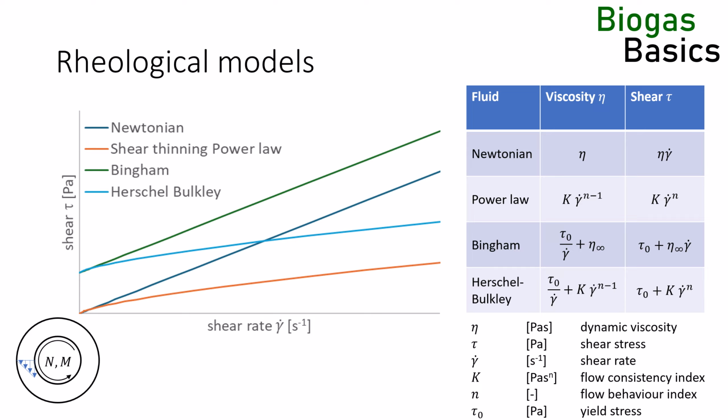For example, the rheological properties of some fluids depend on how much it has been sheared in the recent past. After a fluid has been subjected to a high shear rate, the viscosity of a fluid can be lower for a while because polymers have been disentangled, and the viscosity will only gradually increase to previous levels. This will lead to a hysteresis in the curves in the diagram. I will ignore those effects for simplicity's sake.